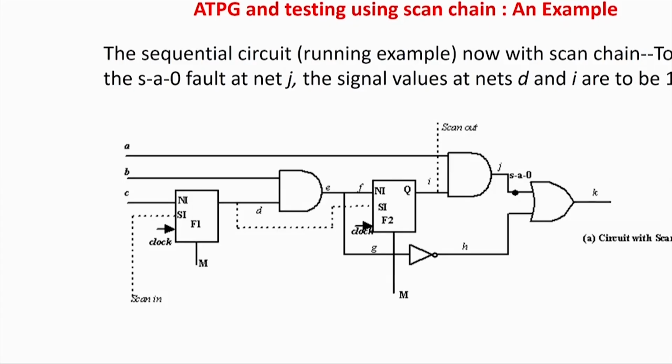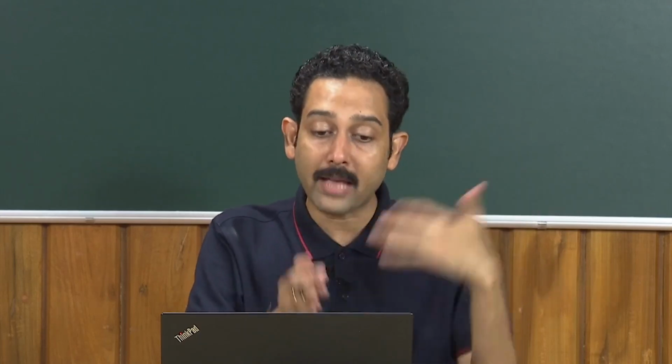It is a more complicated mathematical problem: if flip flops are intertwined without using any scan or set reset, how can you get to the real values required in a very short amount of time. These are more mathematical problems, but nowadays nobody uses it because the story of scan chain has come into the picture. So I think you are able to appreciate that if you are not able to directly control the flip flops, you require more test patterns and also calculation.